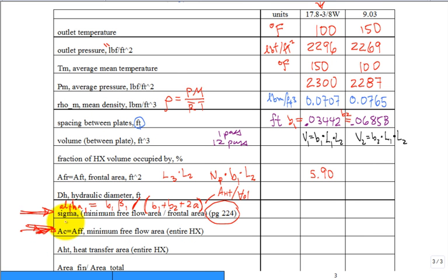What I'm looking for is sigma, from page 224, which is the alpha 1, which you calculate, times the hydraulic diameter divided by 4. So an intermediate step is to calculate the area of heat transfer divided by the volume, that's alpha 1. Do I put that anywhere? Area of heat transfer by the total area is given.